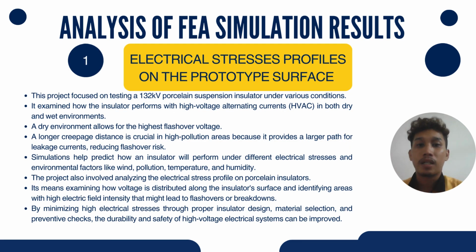Alright, the first analysis of the FEA simulation is the electrical stress profile on the prototype surface. This project focused on testing a 132 kV porcelain suspension insulator under various conditions. It examined how the insulator performs with high voltage alternating current, which is HVAC, in both dry and wet environments. A dry environment allows for the highest flashover voltage. A longer creepage distance is crucial in high pollution areas because it provides a larger path for leakage currents, which reduces the flashover risk.